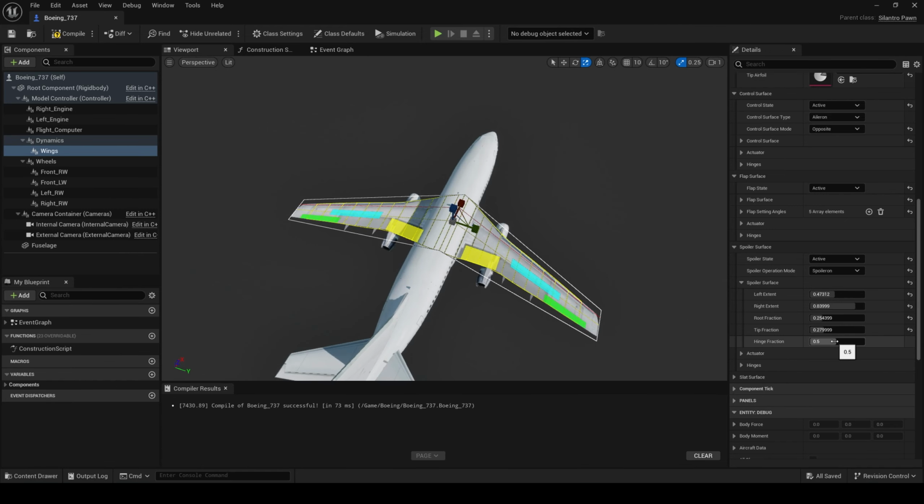So because this is a floating surface, you can actually shift where the hinge is located. So you can move this backwards or forwards, but I think this is roughly around 55% in front. Yeah. The actuator, I'm going to leave this at 50 degrees a second. Deflection limit is about 52 degrees, I think.